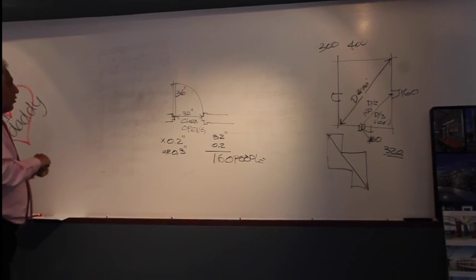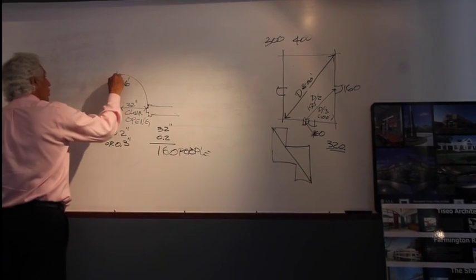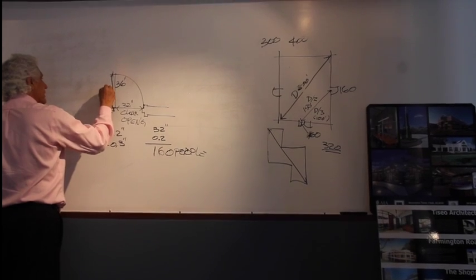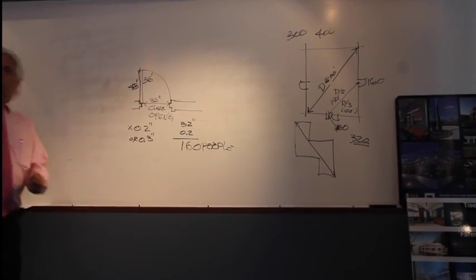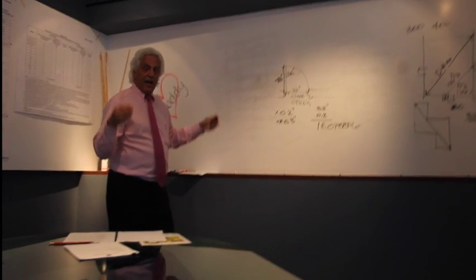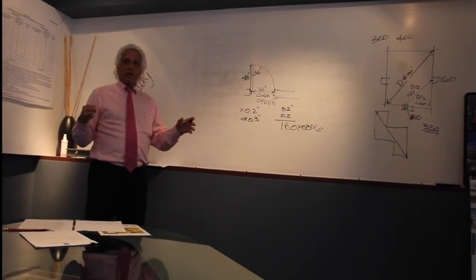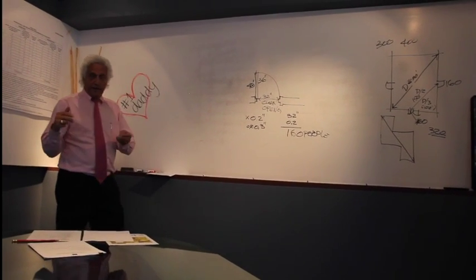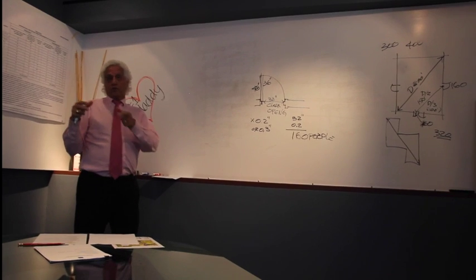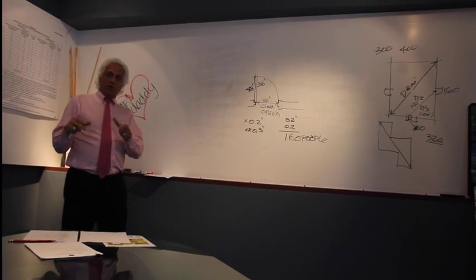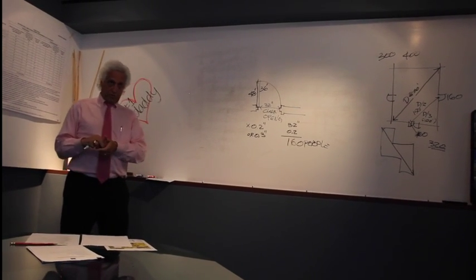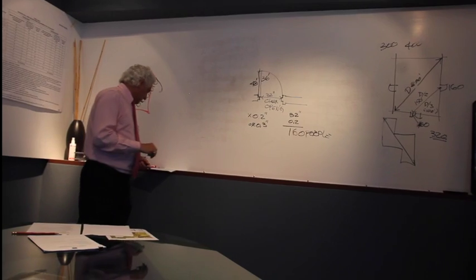The swinging of doors, the maximum size of the door: well, first of all, egress doors have to swing. Secondly, the maximum size of the door is 48 inches as a swinging door. And it has to do with the ability for a small child or a very old person to move the door to swing in the direction of egress.